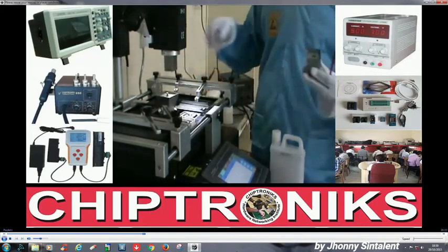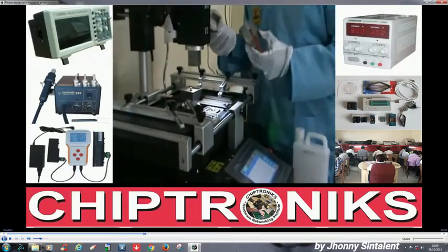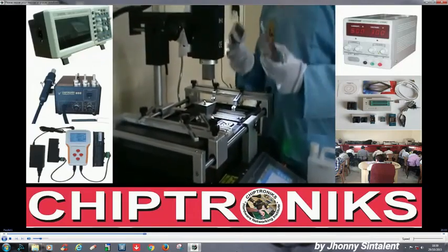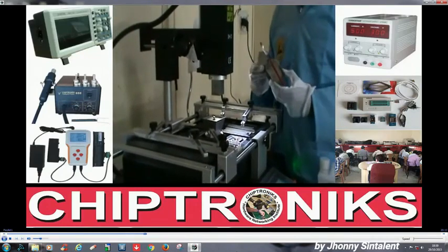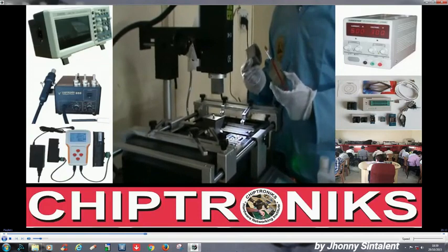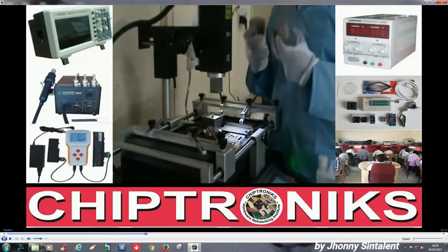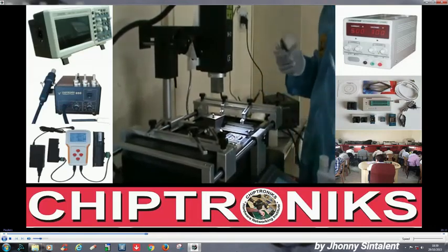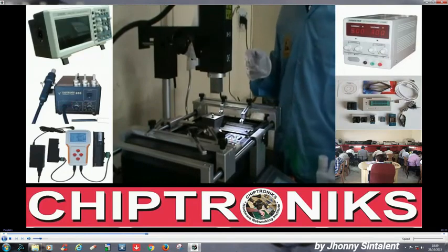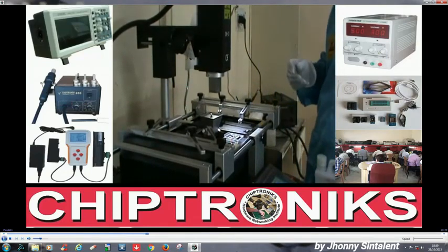And there are 3 types of nozzles for the top heaters. If you have some specific designs, like if you want to remove a RAM slot or some other kind of BGA chip, then the nozzles can be custom designed for that process. But mostly for notebook motherboards, these three kinds of nozzles for a top heater are okay.